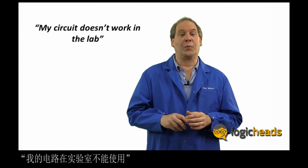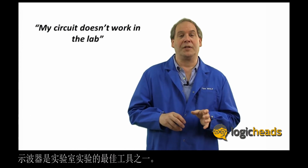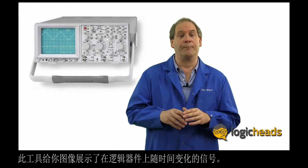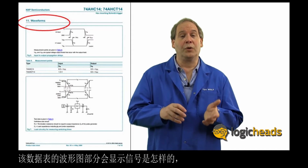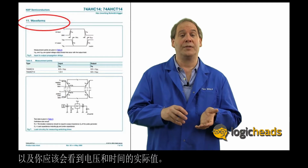My circuit doesn't work in the lab. One of the best tools for debugging in the lab is the oscilloscope. This tool gives you a graphical representation of the signals on the logic device as they change over time. In the same way, the waveform section of the datasheet shows you the way that your signal should look, as well as the actual values for voltage and time that you should see.